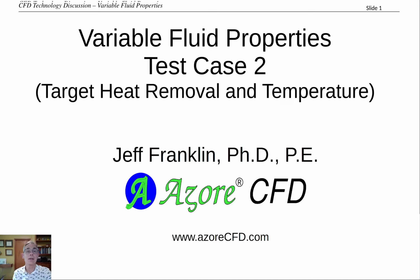The title of this video is Variable Fluid Properties Test Case 2. This is the second of 3 heat transfer cases that we've been looking at and how to set up a heat transfer case in a CFD model. In this particular case, we're going to look at setting up a model that has a specific targeted amount of heat removal, as well as a targeted temperature we want to achieve as the fluid passes through the system.